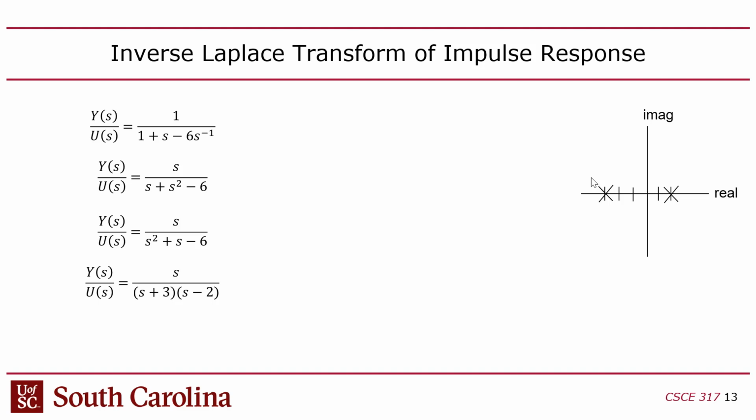The problem is that this is not a stable system because I got this guy over here, right? Now, as I mentioned earlier, this system may be stable for some frequencies, but not for others. All this means is it's not guaranteed to be stable under any input, for example, the impulse or the step.